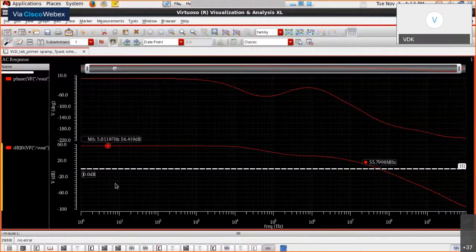This will take some paper and pencil workout to relate these things and figure out how to make use of the technique. This technique is pretty universal and goes across technologies, because everything is based on the characterization results. Then we extended this result by also illustrating the hand calculation and the cross verification of it in simulation for the common source amplifier with a PMOS current source load, and found a pretty good match.